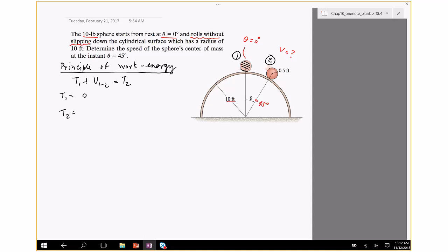Is it pure rotation? It's not actually rotating about a fixed axis. It's translating and rotating. So that's a general planar motion problem, which means I need to use the expression for general planar motion. Okay, this is again taken from the formulas I wrote earlier.